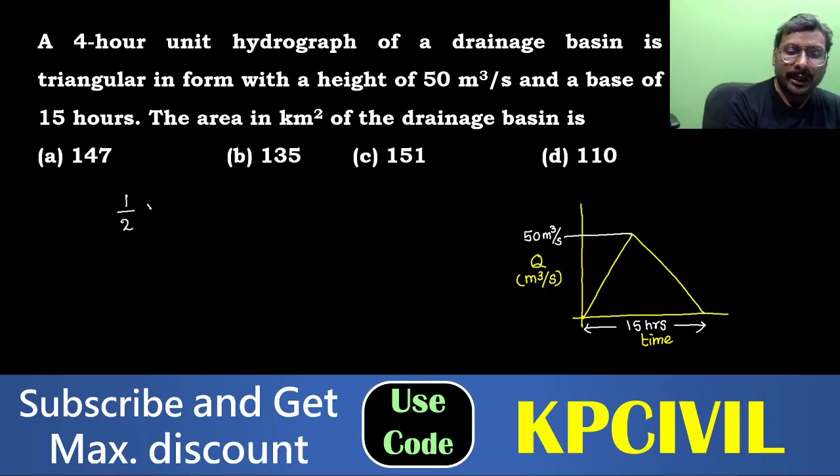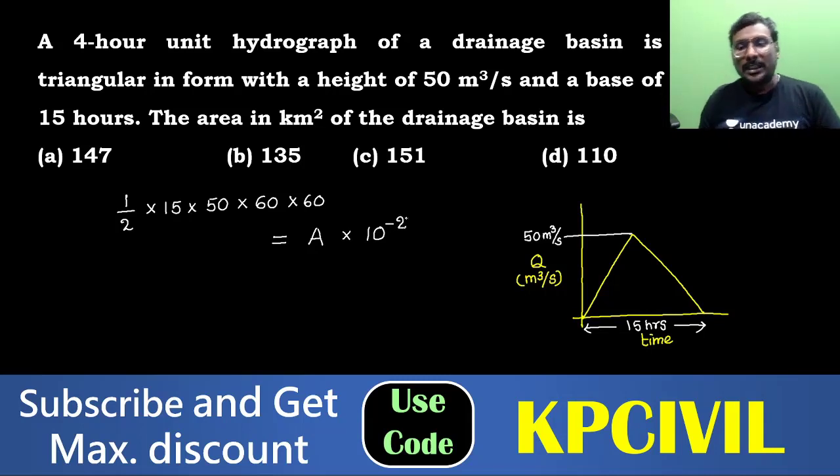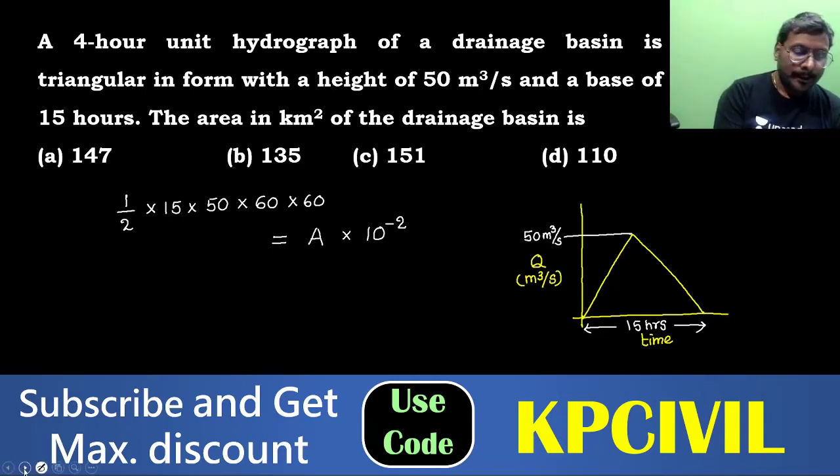Area of triangle is half into time base 15 hours into peak discharge 50 meter cube per second. To convert hours to seconds, multiply by 60 into 60. This is equal to area of catchment into unit depth 1 centimeter. 1 centimeter is considered as 10 power minus 2 meter.